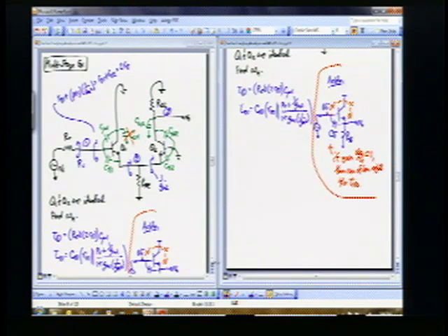All right, so we handled C pi, which I think is probably the most difficult capacitor to handle in this whole thing, because the rest of this just follows through pretty easily here. So now I've got this node 2 that I have to care about, and so I want tau at node 2. And so what's that going to be? What's the capacitor associated with node 2? Can anyone tell me? So look at the circuit here. It's node 2. I already accounted for C pi, so I don't need to include that in node 2 anymore.